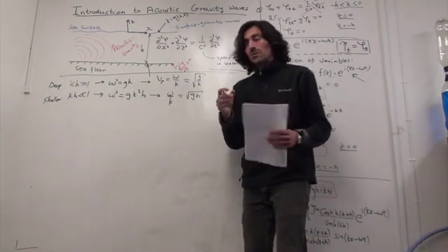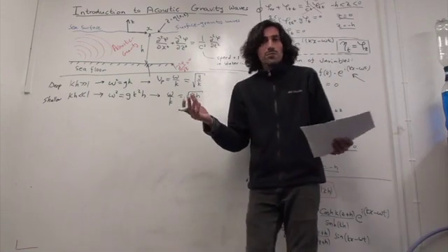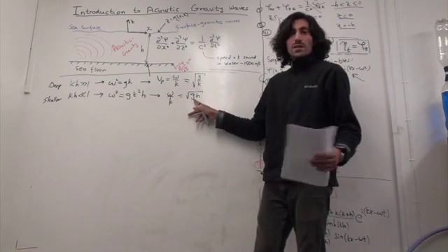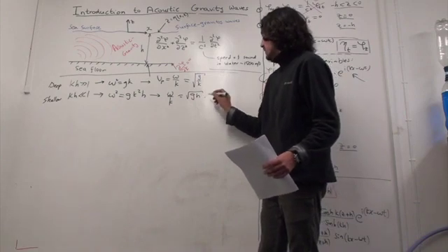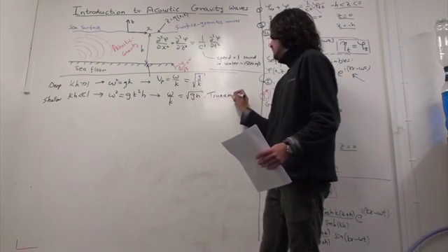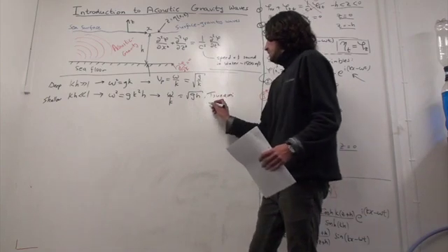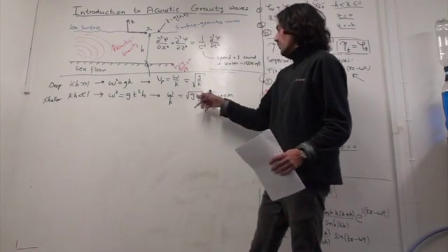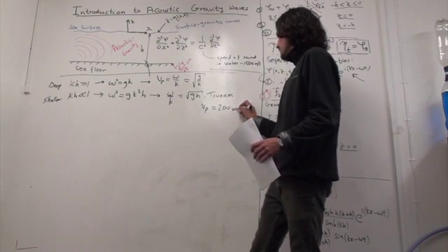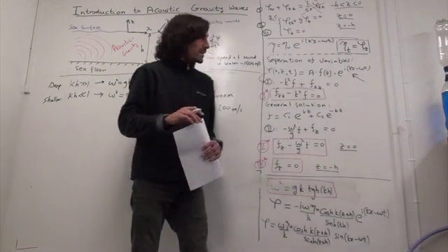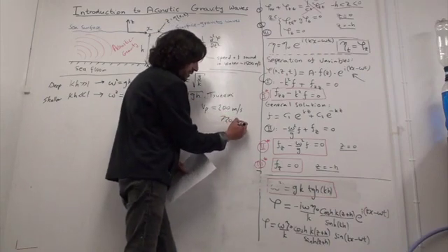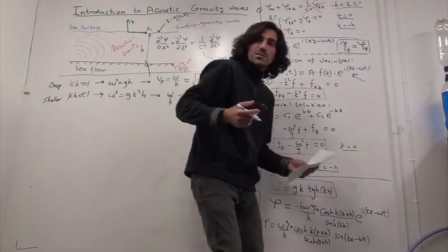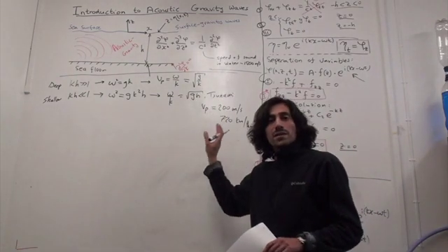So just to give you some feeling, if you consider the average depth in the water, which is 4 kilometers, so 4,000 meters, and take g as 10, so in the case of a tsunami, the phase speed would be square root of 40,000, which is 200 meters per second. That is a large number. This is 720 kilometers per hour. It's almost like a jet plane. It's much higher speed than a regular Cessna.